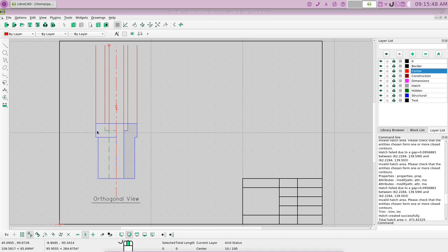Okay, so you notice that all these lines have been extended up. All we need is some horizontals here, and then we're ready to draw our ellipses, or circles they will be on the top section. Okay, so the first thing we want to do is draw a rect or square the perimeter of our unit here, and that is going to be 45. If we turn on our dimensions, we see that's 45. So let's draw that at 45.